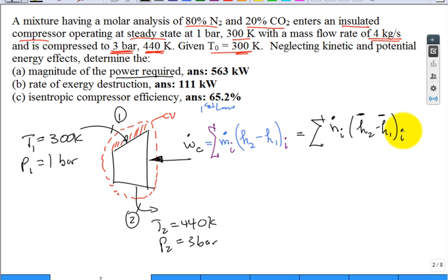What would be the SI units for this H bar? Isn't that kilojoules per kilomole? And if you use the gas tables, the ideal gas tables, where you have CO, CO2, N2, H2O vapor, oxygen, they're going to be on a molar basis. So either one of these work.